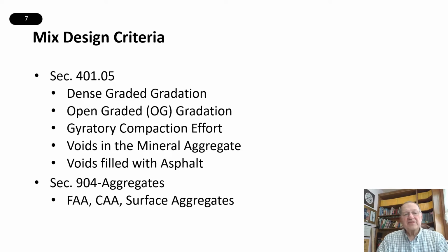Now, the mix design criteria are given in section 401, and it's specifically 401.5. There are gradation specifications that are given for dense graded mixes, for open graded mixes, and there's a table for each of them. The gyratory compactive effort is specified, the voids in the mineral aggregate that we need to achieve, and the voids filled with asphalt.